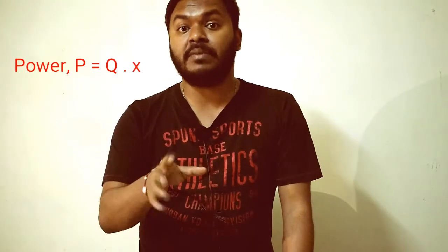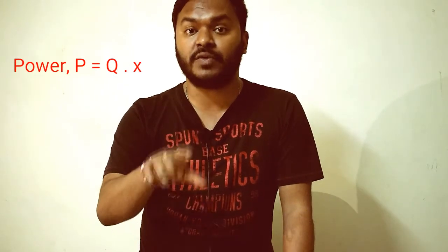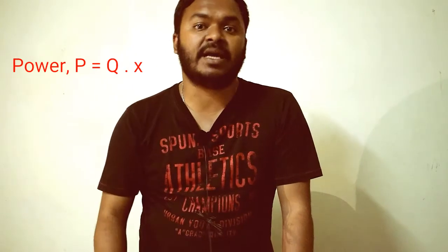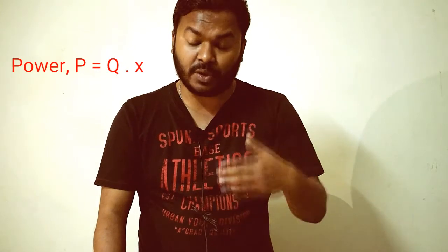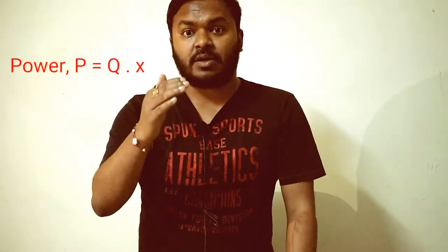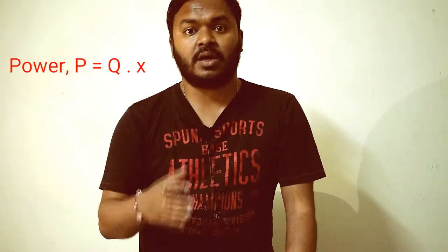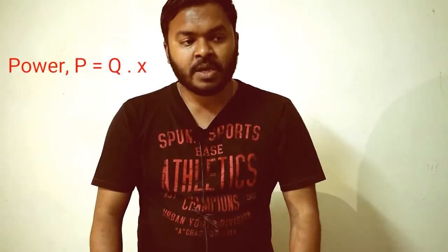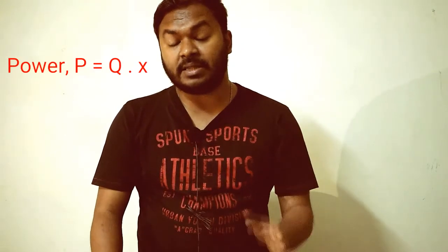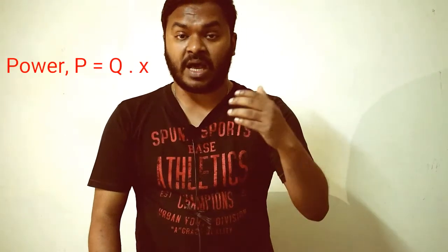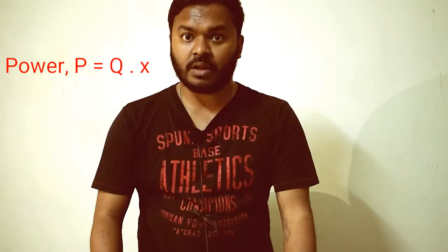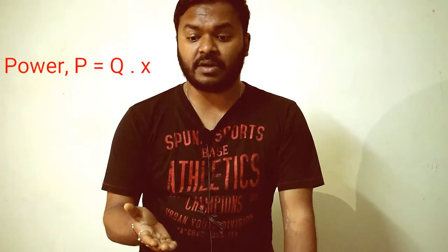We already derived capital Q in the last video, but in this video we will derive the governor power equation, for which we should know how x can be related. When there was no change in speed, it was moving at omega, with a governor height h. But this time there is a lift and the governor sleeve goes up, so there will be a change in height. Due to this difference between h and h1, this x will come out.